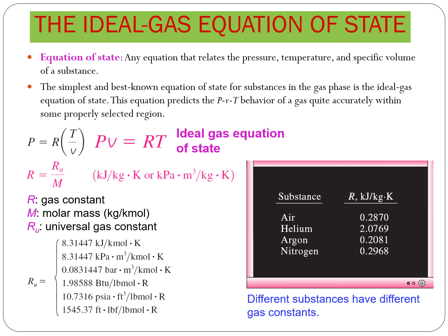The ideal gas equation is just Pv equals RT, where v is the specific volume. Remember, you should know that. And then you should know exactly what the unit should be and what each parameter means. That's where you get it wrong. So here P has to be an absolute value. In SI units, it is Newton per meter square, and the specific volume is in meter cube per kg. R is the gas constant.